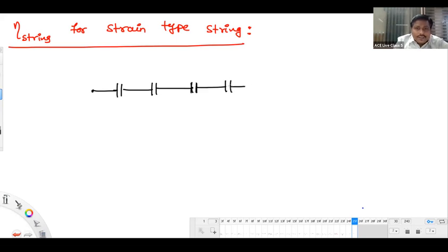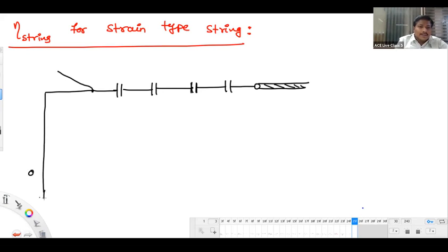This will be the capacitor distribution model, and this is a tower, and it's a conductor. So the tower is getting grounded and operating at zero potential, of course. Each disk will have the same capacitance value C. Next, please listen all of you. These are the link pins formed, 1, 2, 3 link pins.